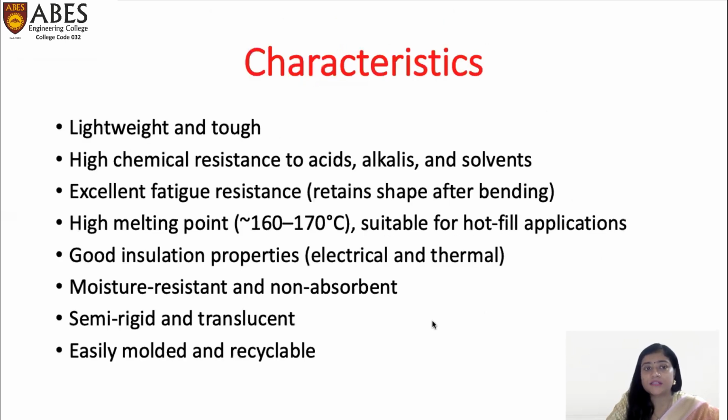And the characteristics include they are lightweight and tough. They have high chemical resistance to acids, alkalis, and solvents. Excellent fatigue resistance. That means even if you put a lot of mechanical pressure, they will maintain their shape for some time. They have a high melting point, suitable for hot fill applications. They have good insulation properties, electrical as well as thermal. They have moisture resistance and are non-absorbent. They are semi-rigid and translucent, and they can be easily molded and recycled.